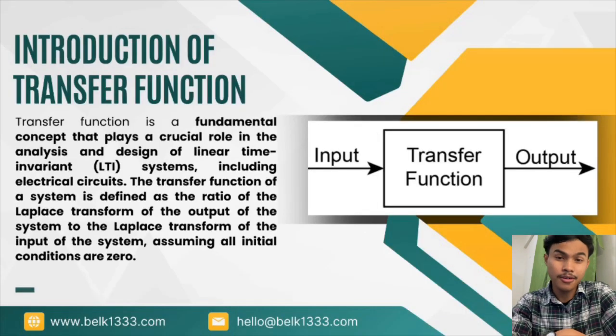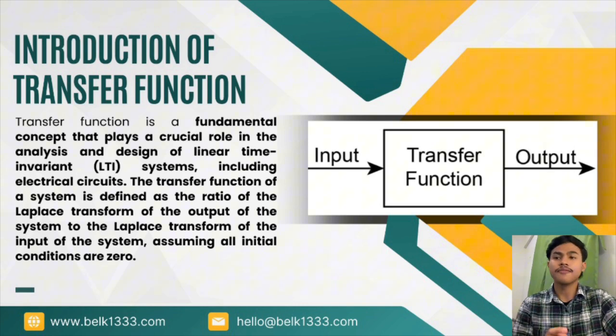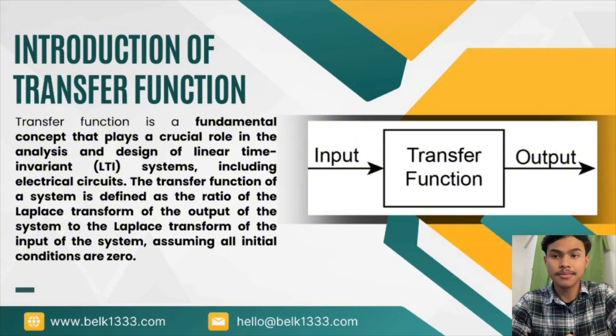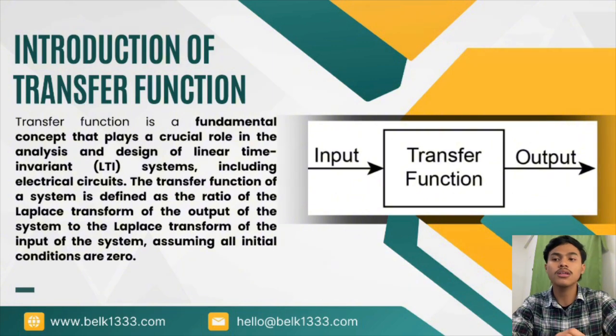So next, for the starting, let me introduce what a transfer function is. Basically, a transfer function is a fundamental concept that plays a crucial role in the analysis and design of linear time invariant, or what we call LTI, systems. The transfer function of a system is defined as the ratio of the Laplace transform of the output of the system to the Laplace transform of the input of the system, assuming all initial conditions are zero.